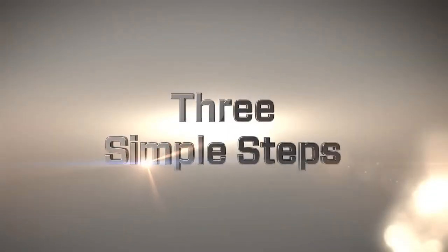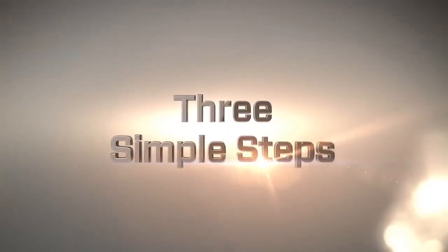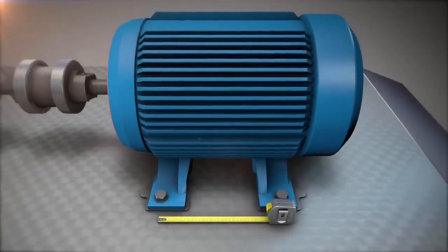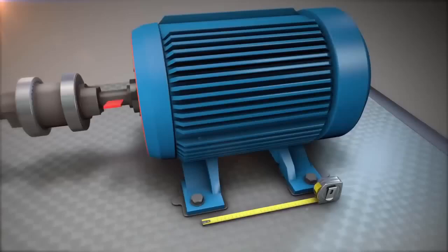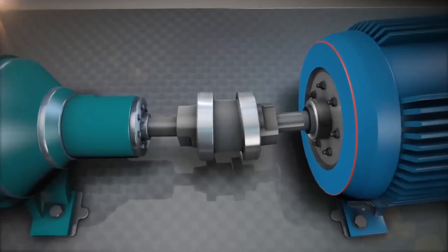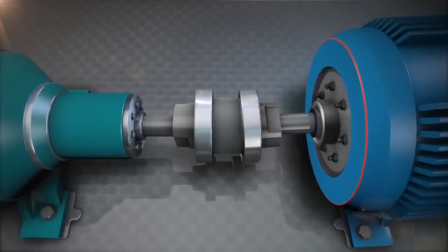The process of precision alignment can be broken down into three simple steps. First, measuring and inputting the machine dimensions. Second, measuring the misalignment between the shaft center lines of rotation. And finally, calculating the necessary corrections and aligning the machine to be moved.